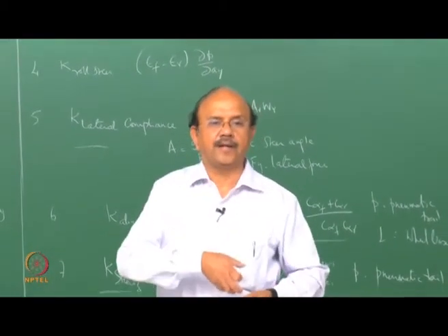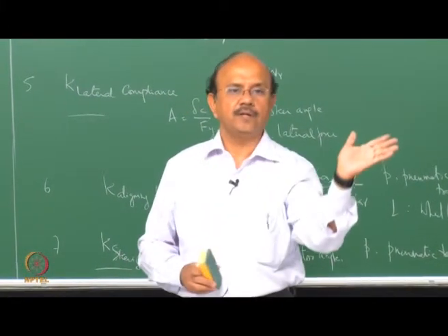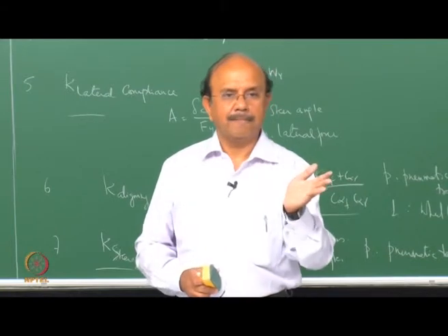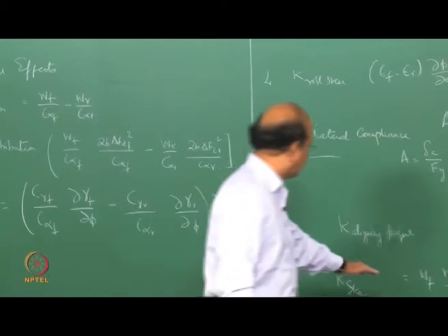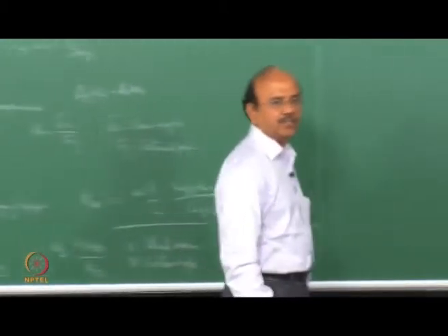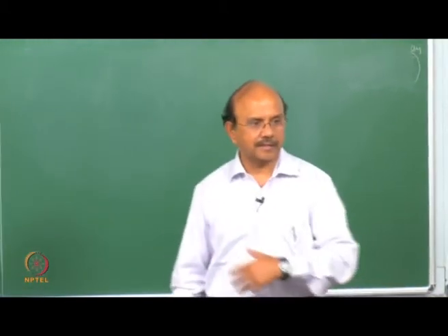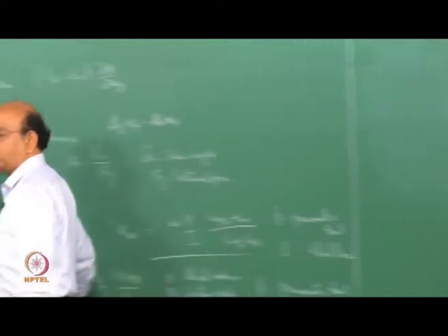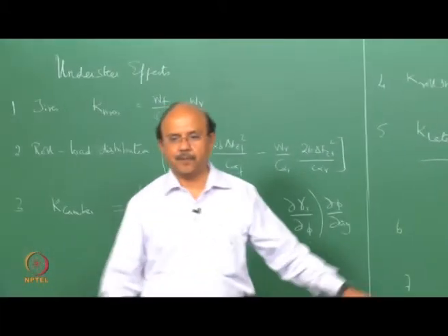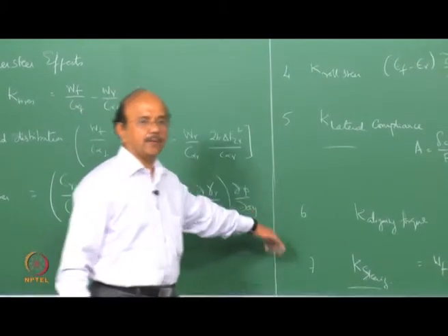The same force is applied at the rear, but because the yaw center is now shifted, you will have a tendency to go to the right. So there is a difference. Here also the compliance of the steering system comes into the picture. That's very important, and we're going to see that as well. In fact, I have to spend a lot more time on this. I don't have that time now, so I refer you to Gillespie's chapter on steering.